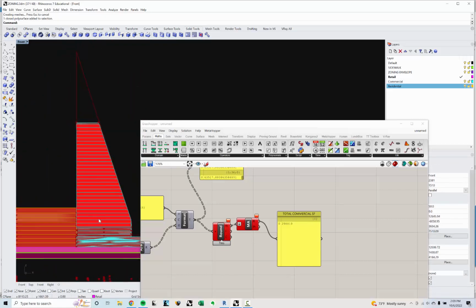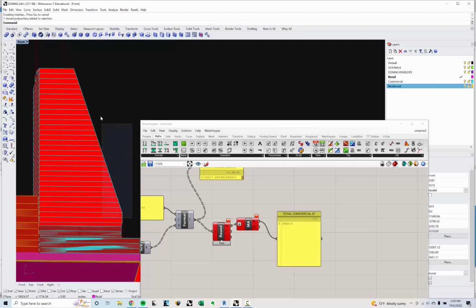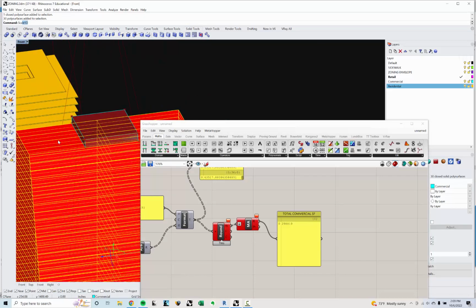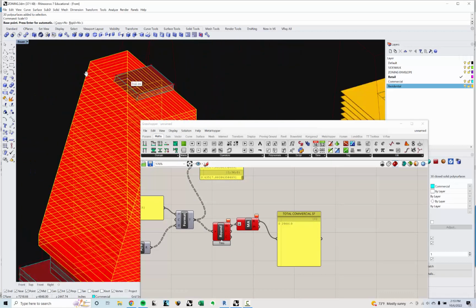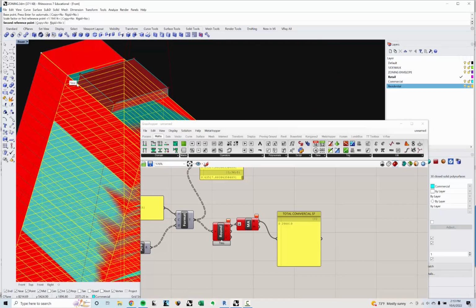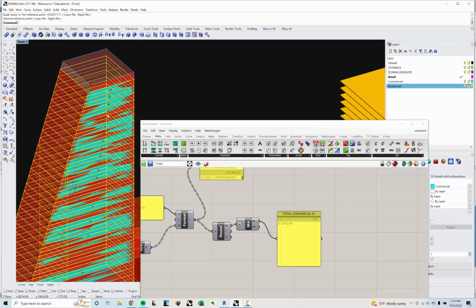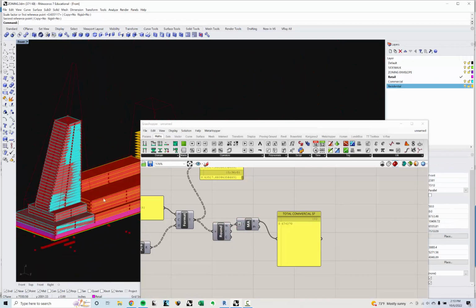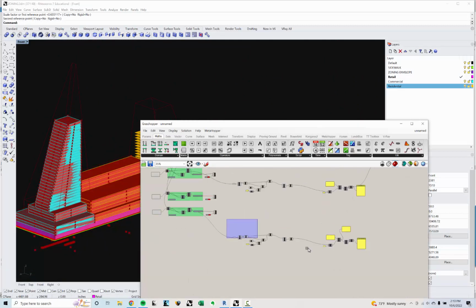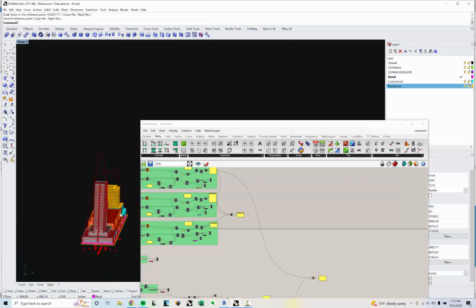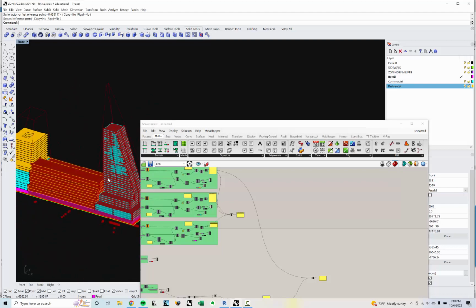Let's just, for the purposes of making this work, select all these. And I'm going to scale 1D this way, and then scale 1D this way. So I'm leaving a lot of square footage on the table, but now I've got all of my compliant square footage in there. And you copy and paste this, tie it into the residential, or sorry, into the retail, and then you can pull all this together, and now you can get a pretty good visualization of your project.